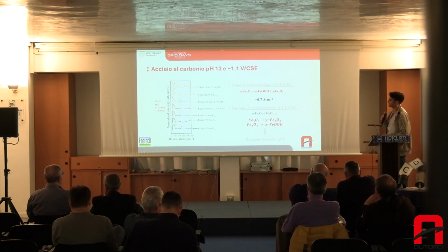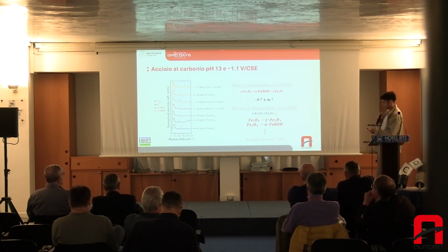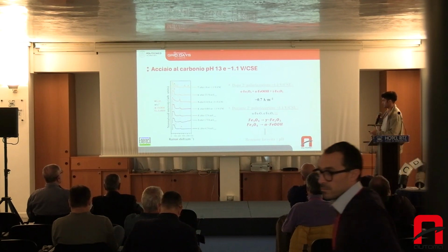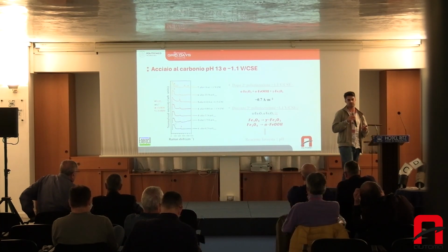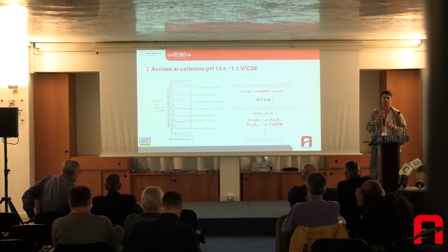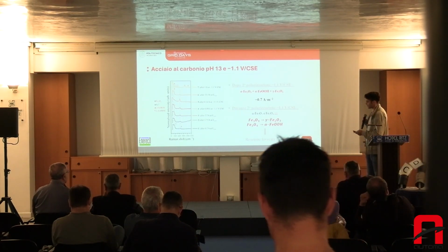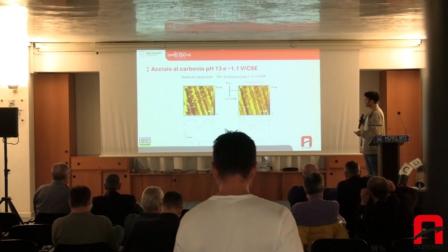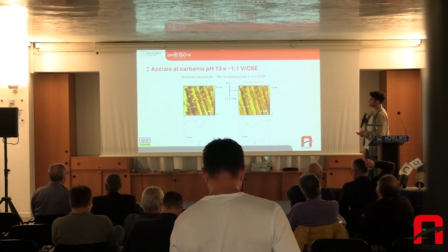These correspond to these stages. So beyond a certain level, the magnetite is no longer stable, and you have these two oxides, less protective than magnetite. So with excessive polarization, we have changed the materials that get developed on our steel. This is what I was talking about before.